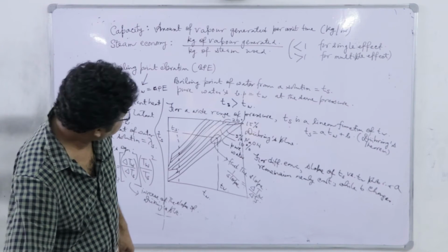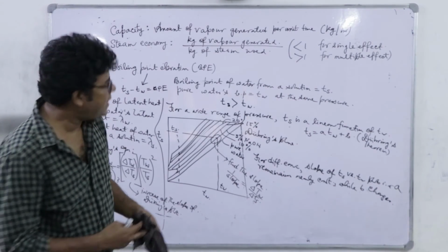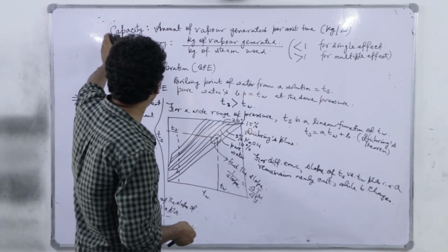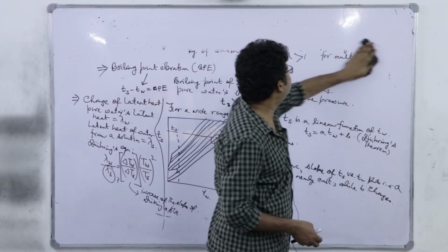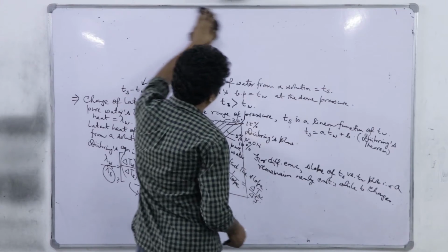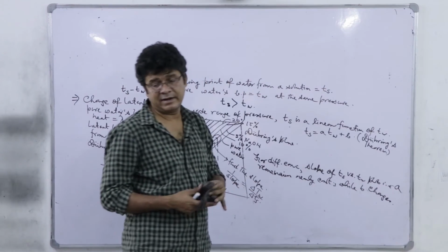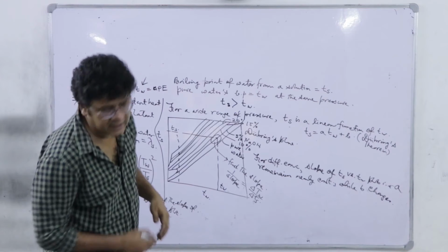Next, the important terminology here, or phenomenon rather, is the boiling point elevation or boiling point rise because of hydrostatic head, and that we refer to as correction for hydrostatic head.